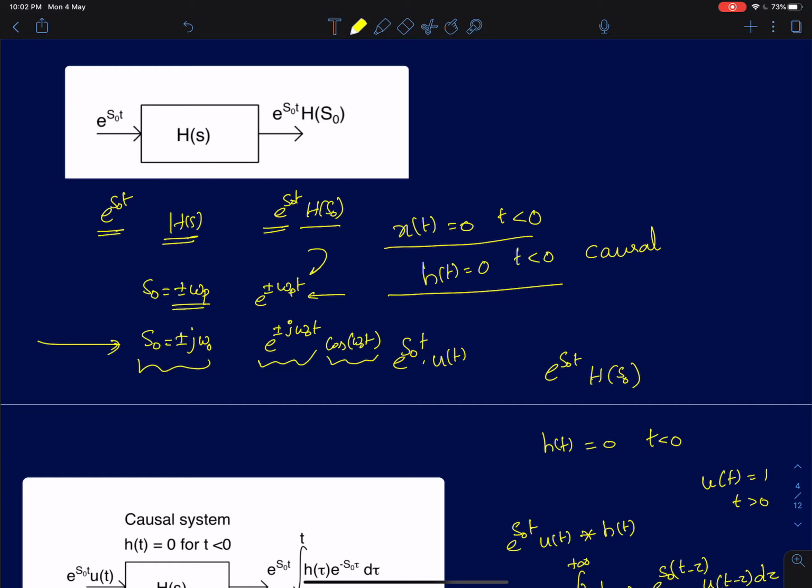Now in this lecture, we will add certain practical constraints. We would rather want to see what happens when I actually apply an input at t equal to 0. Normally in any practical circuit or system, say we are feeding an input from a function generator, we usually turn on the function generator at some instant, and so the circuit will see as though the input is being applied to it suddenly. So we are going to say mathematically that the time at which the input is applied is t equal to 0, and that the input was 0 before t equal to 0.